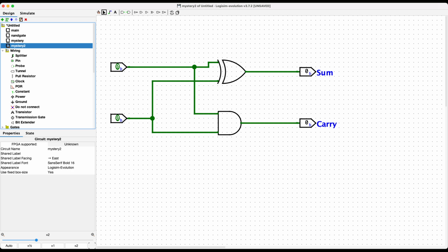We need more than that. And that circuit is what we'll call a full adder because it takes 3 inputs and produces 2 outputs: 2 bits in plus a carry in, and a sum out and another possible carry out. Because in this case, for the example I picked, 1 and 0 with the 1 carry from before, I'm going to get a sum of 0, but I will still generate a new carry that would go to the next position.